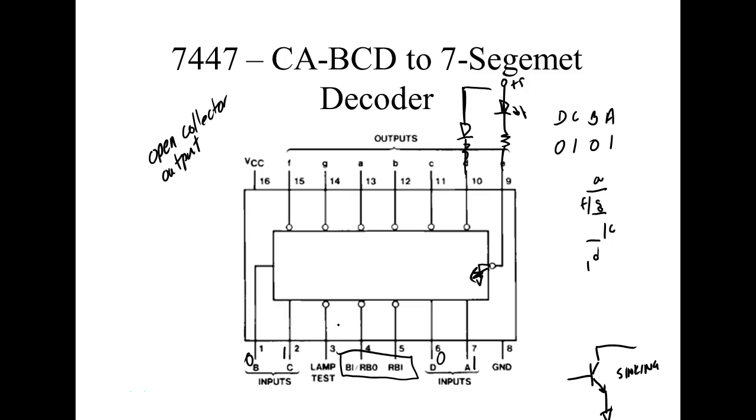So they said, why do I need to run a 7447 for every LED? Why can't I turn this guy on or turn it off, turn it on? We call that ripple blanking, by the way, where they can blank this display, turn on another one, right? That makes sense? Blank this and then turn on it.